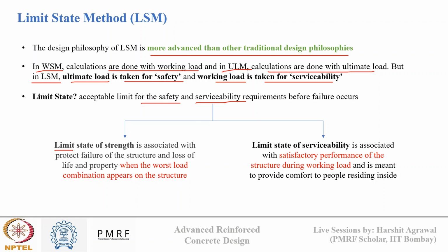So when we design for safety, we use ultimate load in design so that my structure is safe against the worst loading combination possible. And for serviceability, to check for cracking or deflection, we take the service load into action, and we check whether my structure is performing satisfactorily at the service load condition or not, so that the people who are using the structure are in comfort. Okay. So that's how we take both service condition and ultimate condition into design in limit state method.